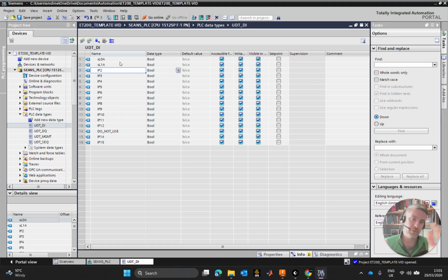And then as you move to the right, you encounter the one on cylinder A that deals with the extended limit. And A is on the left of B, because we're going from left to right, A then B. So for that reason, XL0B comes after that, XL1B comes after that. Let's go for a third cylinder, XL0C, XL1C.